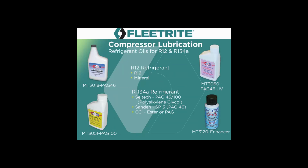The oil itself, there's several different types of it out there. Back in the R12 days, we used mineral oil. It was a very universal oil. As systems converted from R12 to R134a, we got a new refrigerant, so we started getting new oils. It started out as an ester oil. Ester oil has pretty much gone out of style these days, and all of the compressor manufacturers are recommending and using a PAG oil, polyalkylene glycol. And when you go looking for PAG oil, you'll notice that there's several different types of it out there. There's a PAG 46, a PAG 100, a PAG 150.